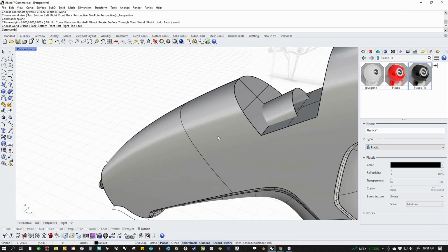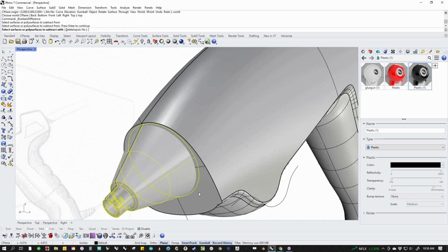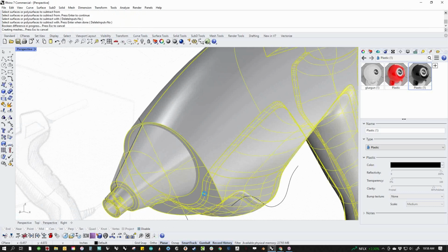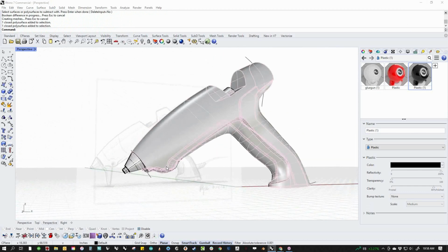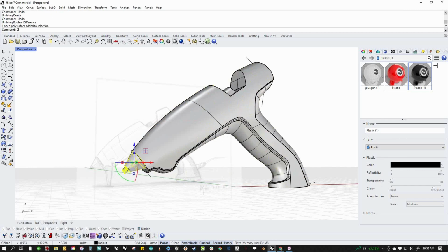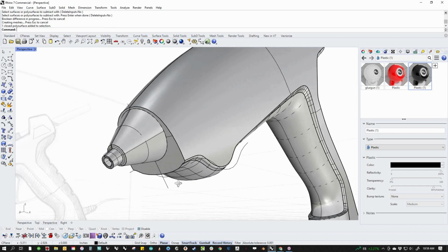All right. So let's do that, and I'm going to just Boolean subtract this using this, and I'm not going to delete the input. That way these two fit together. And it looks like I had some normals issues there. Let's fix that. If I cap it, it's a closed object. Now I can do that. The problem was my normals were facing backwards, so there we go. So there's that.